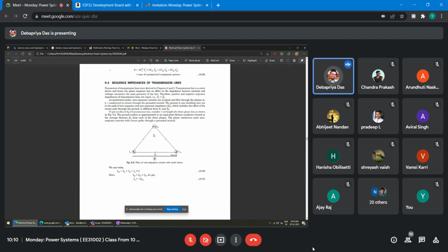These things are very simple. Only one thing you will keep in mind, that the zero sequence current generally goes to the ground, right? That should always be in mind. Actually, this way components are broken such that fault calculation, everything to some extent will be very easy, right?